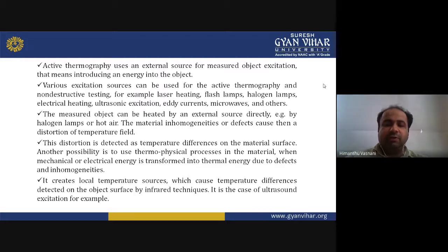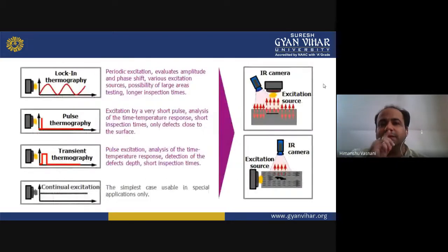In this way, this active thermography works. Then you can see some kinds of thermography discussed on the left hand side, and on the right hand side, you can see how they are done. Like there is lock-in thermography that we just discussed, and it gives you a periodic excitation, evaluates amplitude and phase shift, various excitation sources,